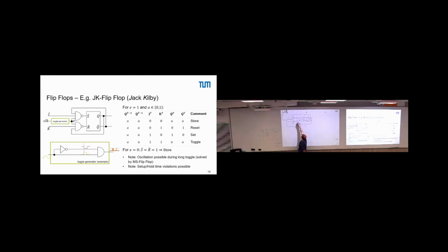And this will cause that this internal state here goes into a reset. No, R bar is 1, and then the internal state is set, right? So we are in a set state here. Q should be 1. And the whole thing is effectively in the fixed state. Now we have Q at 1 and Q bar at 0 in the next state.